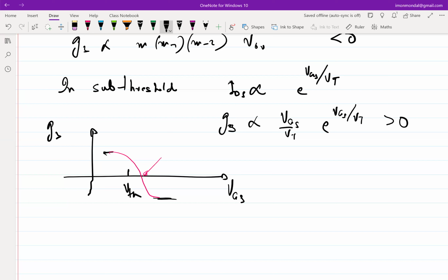It is calibration, in fact. But the issue in this case is that this cannot work for high power circuits, because for high power circuits you need a very high value of VGS, obviously, because you want to extract maximum power out of your MOSFET. This clearly works somewhere around subthreshold, where you are coming out of subthreshold and moving into inversion, so a fairly low amount of V overdrive. So that is one limitation.